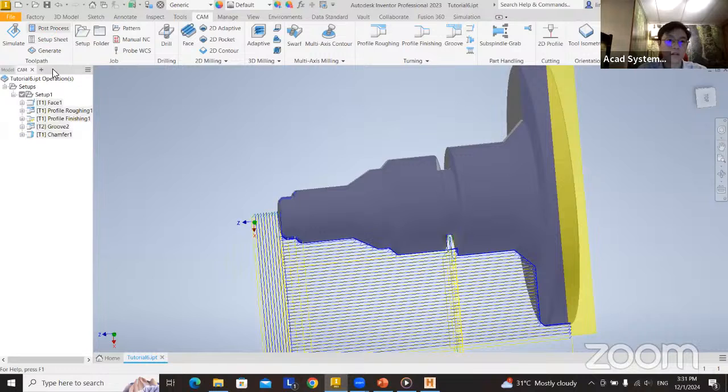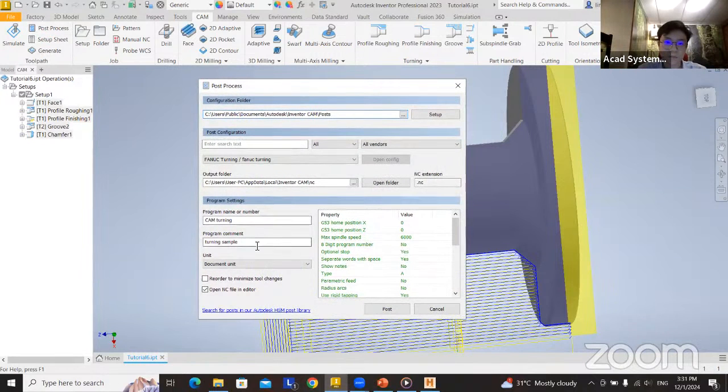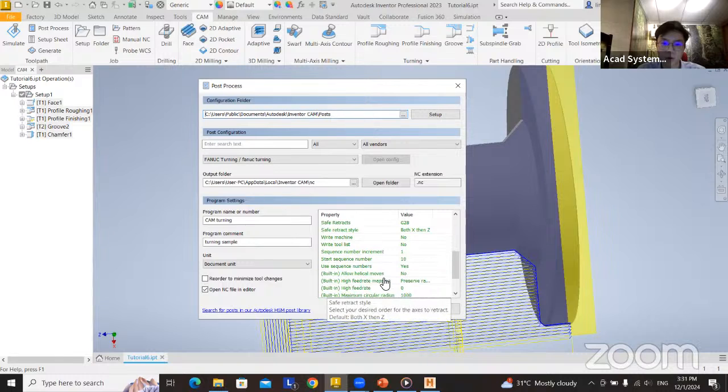After you have gone through all of these settings, over here you can actually change the value of the home position for your tools, your spindle. And if your spindle has a little offset, then you can also specify it over here. And then there are cases where there's sequencing, like line number one, number two in your G code, right? You can also disable it through this setting, where use sequence numbers, you can just turn it to off, no, and then you can change the sequence number increment, and then just click on post.